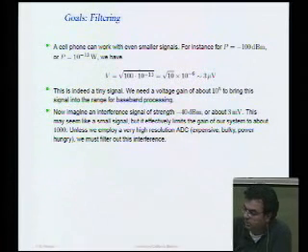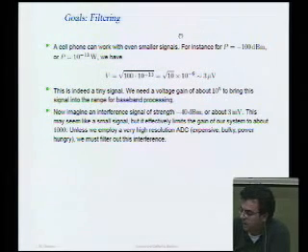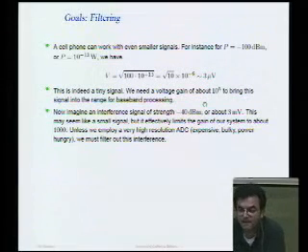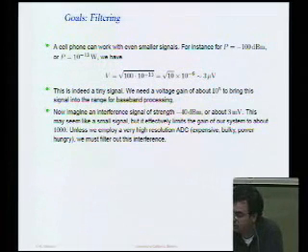Now the other point about communication is that while you're receiving, in that near-far situation that we described, while you're receiving this tiny signal, let's say you're also receiving another signal, which is an interference that's minus 40 dBm. Now again, that's only about 3 millivolts. That's a pretty small signal, right? Nothing to worry about, especially when we look at distortion and large signal behavior of transistors. Yeah, 3 millivolts is a pretty reasonably small signal. But the problem is it's so much bigger, right?